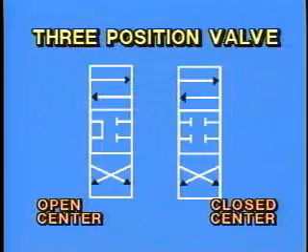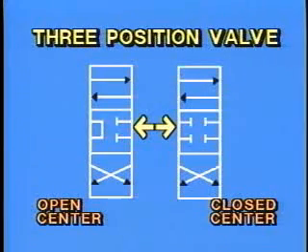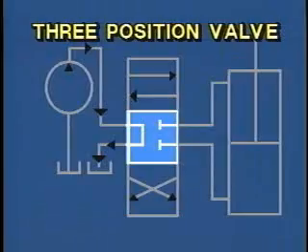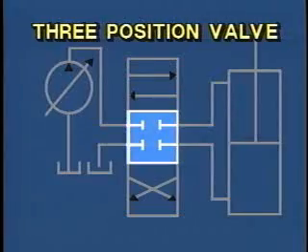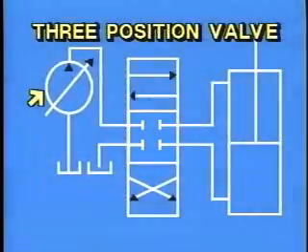Three-position valves will have a centered or neutral position. The centered position can be either open or closed to flow. The open center is usually used with a fixed displacement pump, and the closed center is usually used with a variable displacement pump.